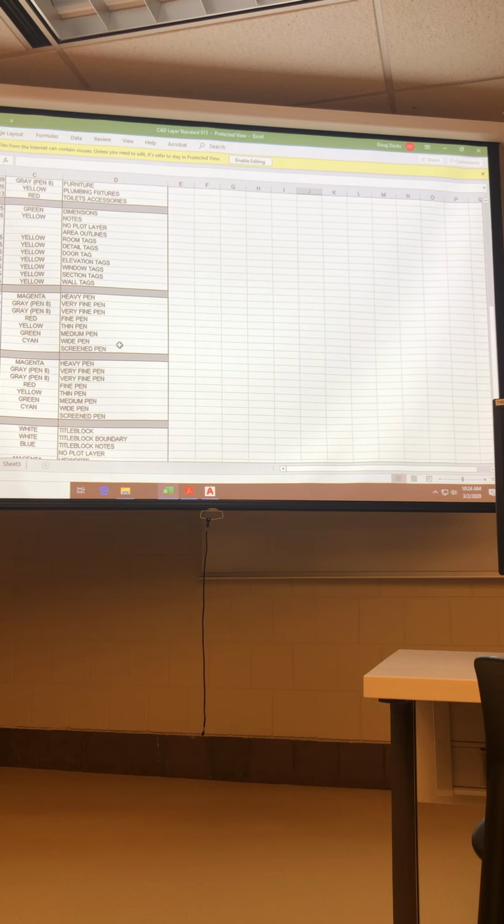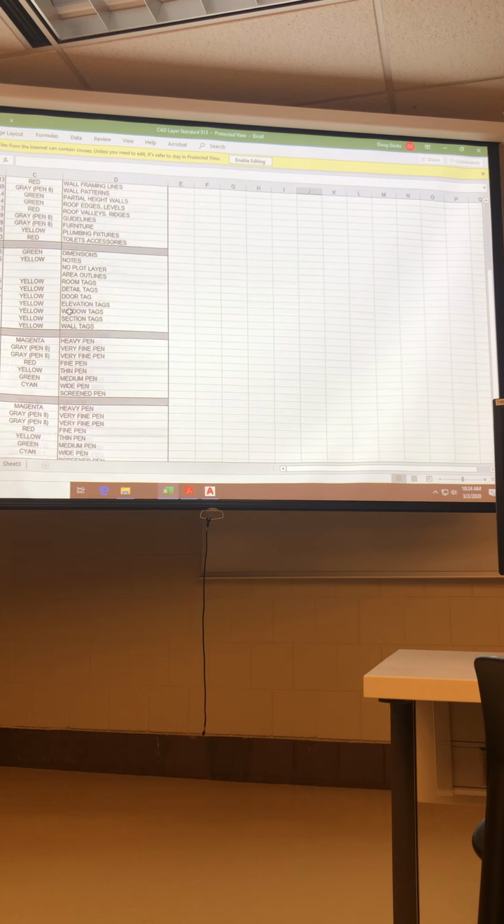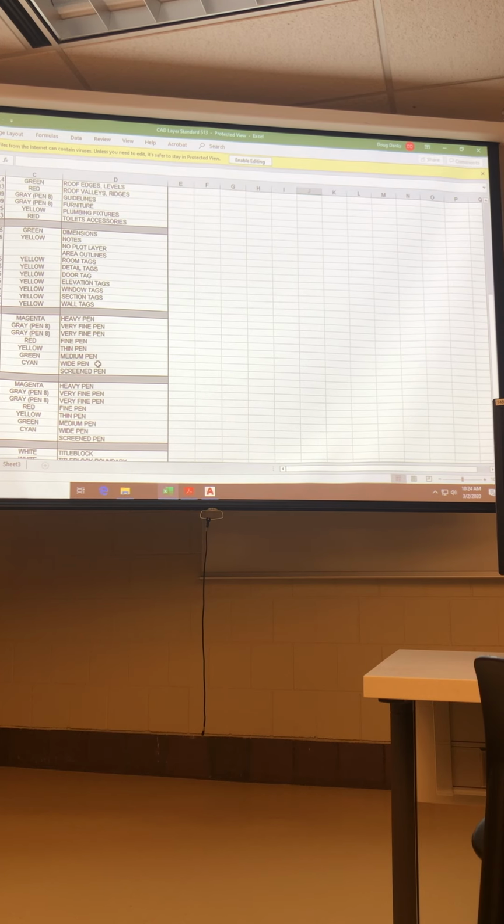With the floor plan drawings, everybody was using this group of layers primarily under the floor plan section of our layer list. What we're going to use for this next drawing, and actually for the elevations as well, is the elevations as sections area of the layer list. So it's just a few. Go ahead and actually create all of those layers right at the start, because we will use all of them. Get them in there, and then we can start drawing with them right away.